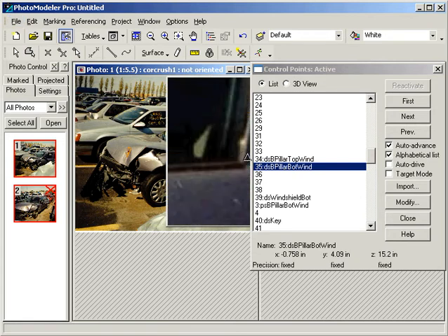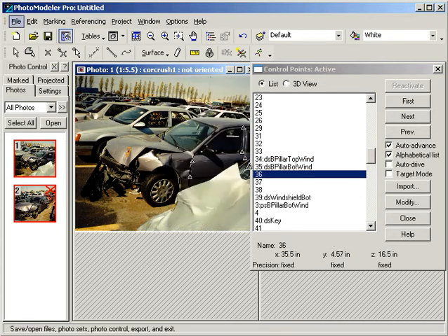It is very important that we mark these control points in the correct corresponding positions. This is why it is important to give the points in the control point file a unique name that will help you find the correct position it corresponds to. Incorrect or inaccurate control point marking will result in poor results when inverse camera processes.